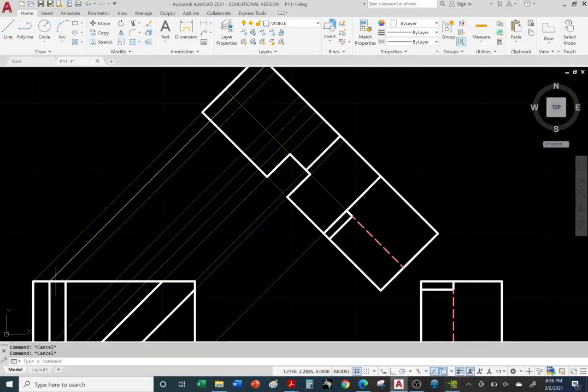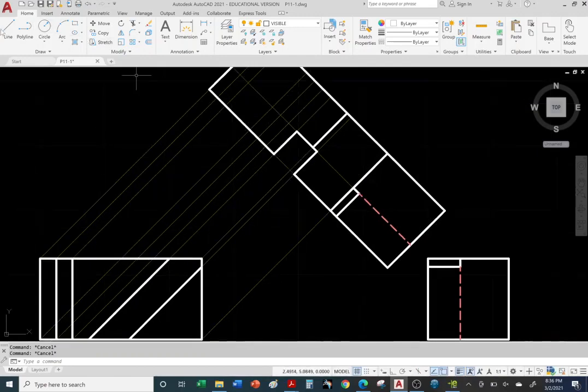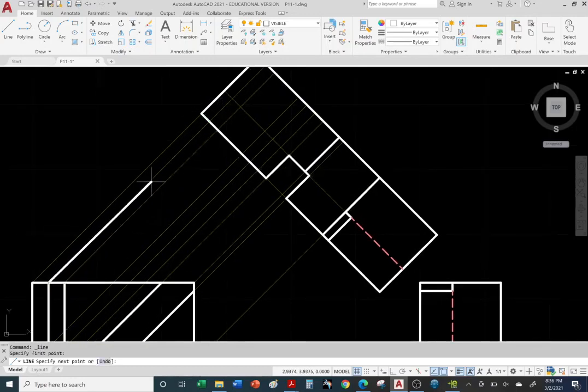Okay, so we're going to come over from the front view. Let's use the line command, visible object layer. From this corner, we're going to follow the yellow construction line, follow the yellow brick road, right click. And we know that this is the size of the opening. So we're going to follow this construction line, right? Follow it. There it is, and close it. Right click enter, and now we can adjust the visible object line to the correct length. There it is. Hit escape.